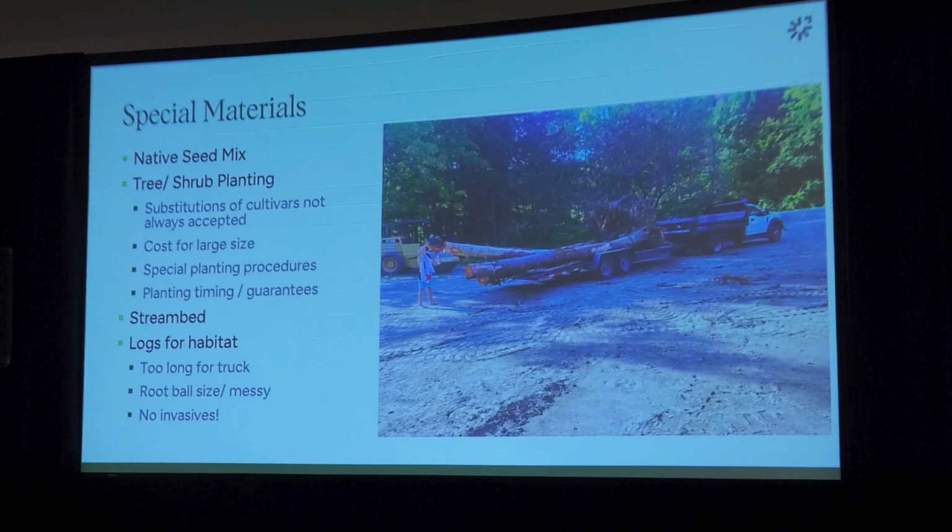Really making sure that these items are sourced early and approved early for a lot of different reasons. The native seed mix that we will often use might take a while to get to the site. And if you wait until you want the contractor to actually apply it on the ground, and then they have to go through a submittal process, it can hold things up, and you wind up not getting your restoration done when you want to.